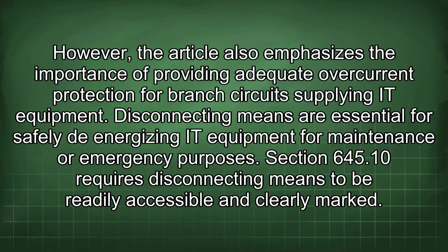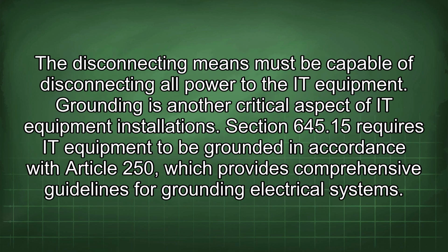Disconnecting means are essential for safely de-energizing IT equipment for maintenance or emergency purposes. Section 645.10 requires disconnecting means to be readily accessible and clearly marked. The disconnecting means must be capable of disconnecting all power to the IT equipment.